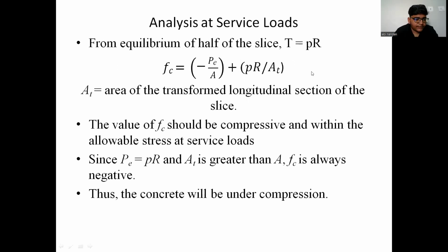Analysis of service load. The tensile stress due to the internal pressure can be calculated from the tension T from equilibrium of half of the slice. We are not considering the full circle. We are considering half of the circle, where T is equal to PR, where R is the radius of the mid surface of the cylinder.